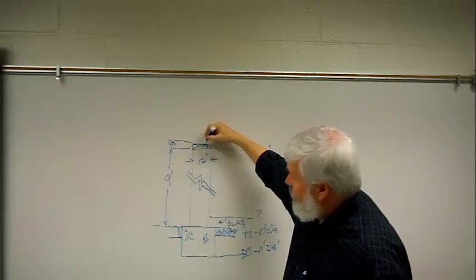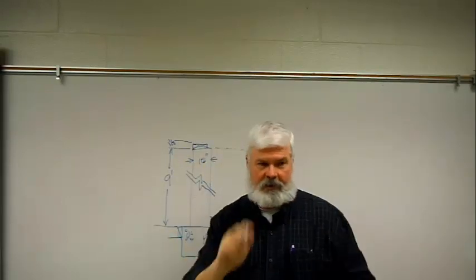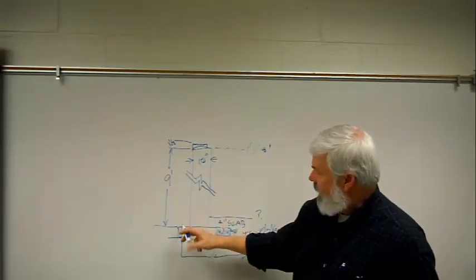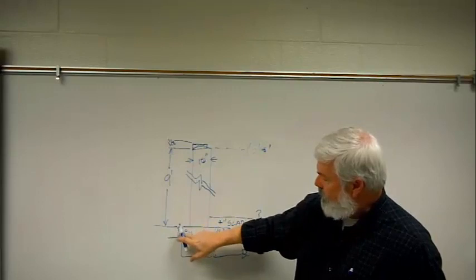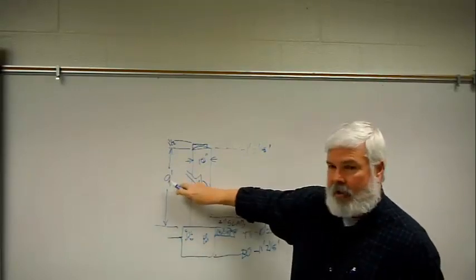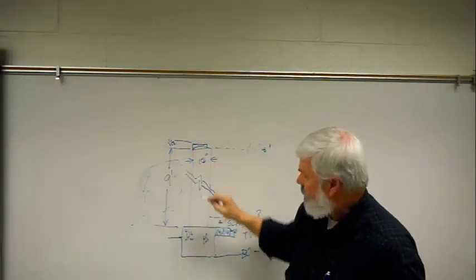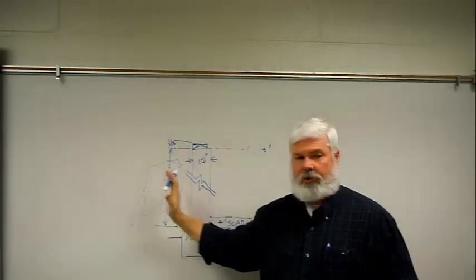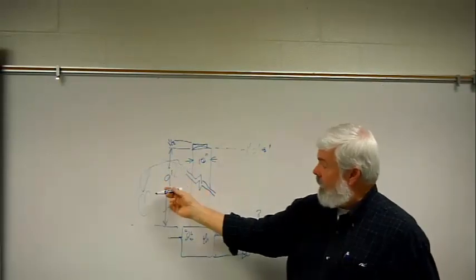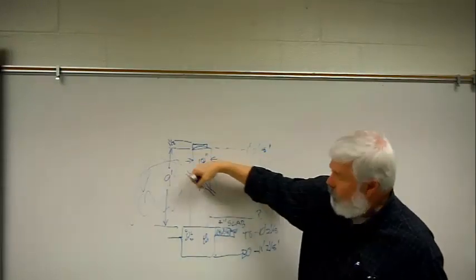But on top of the pressure-treated sill plate now, and a couple other side notes, because this is something I want to touch on too. If this is the inside of our basement, and this is the outside of our basement, after you strip these form boards off, what's going to be out here? Dirt. There's going to be a whole lot of dirt out here. And the pressure of that dirt is horrendous when the dirt is wet. What kind of forces is that going to apply on the wall? I'm giving you a hint. It's going to try to move the wall this way.